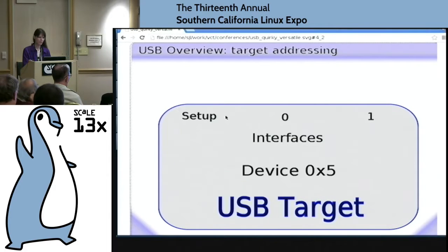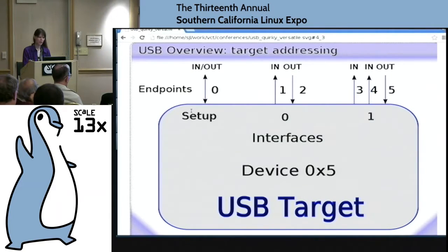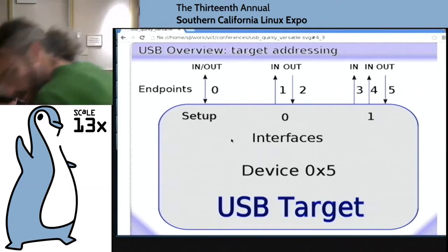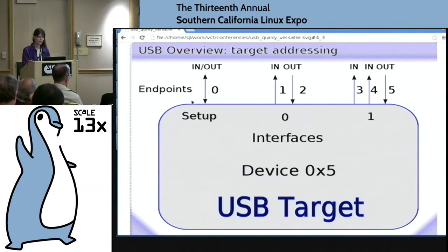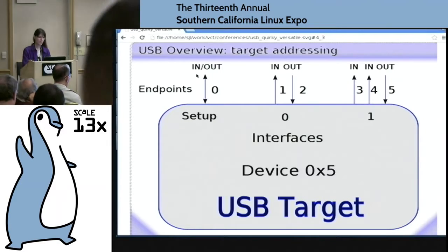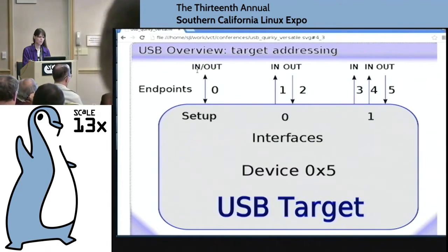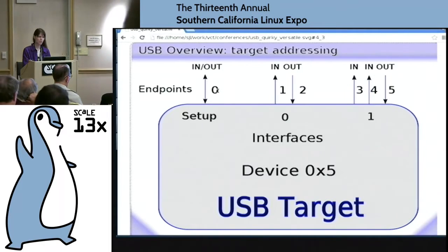But of special interest, actually, is the setup one, because everybody has to have an interface that you use for that enumeration stage, which is before you have your temporary alias. You have to have a way to talk to the host just to tell it who you are and get the device number assigned. And you have this funny endpoint 0.